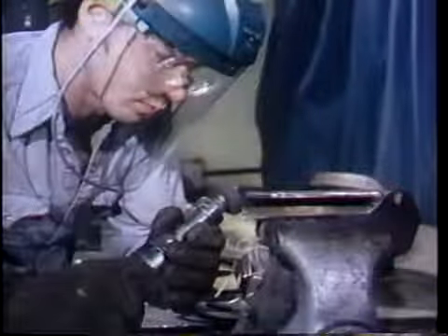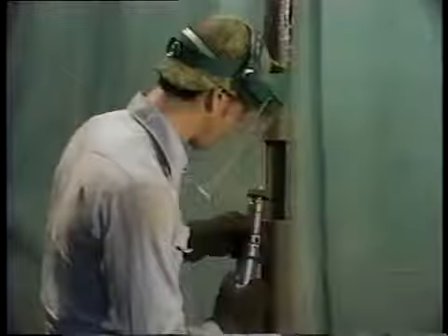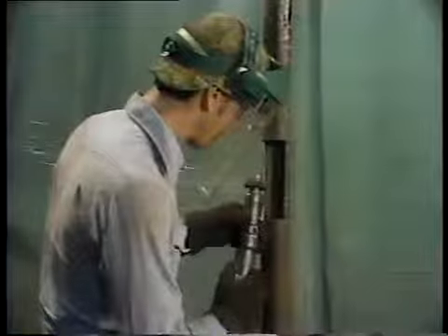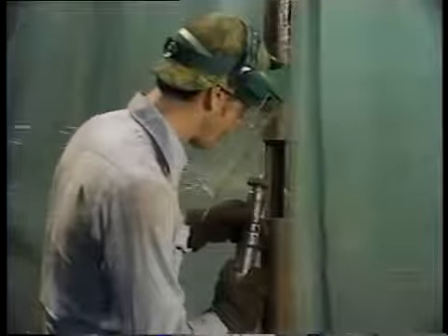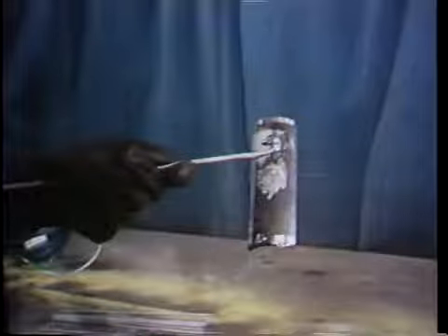Before welding, the edges of the replacement piece and the edges of the tube opening must be beveled and ground smooth. Once this has been done, the replacement piece is ready to be tack welded in place. To do this, a welding rod is first tack welded to the center of the patch. This acts as a handle for holding the patch while it is being tacked. The welder then tack welds the patch in place.